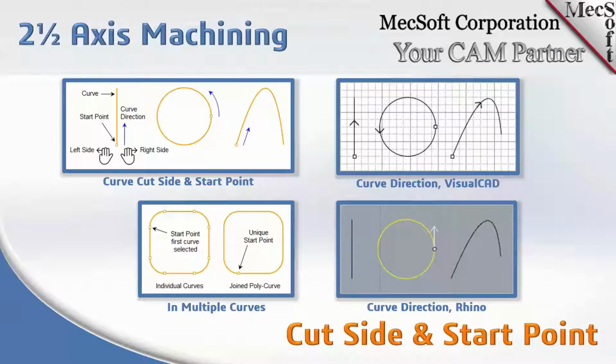A quick note: this slide applies mostly to the profiling machining operation, because the curve direction, right side and left side, all come into play only in profiling. As we mentioned, in facing and pocketing, the closed curve determines the side, because in pocketing it's always on the inside, and in facing it's always on the perimeter. So we're really talking about the profiling machining operation here. It's important to know. Thanks, Joe. Also, an open NURBS curve is the same. You have a start point and you have a right and a left.